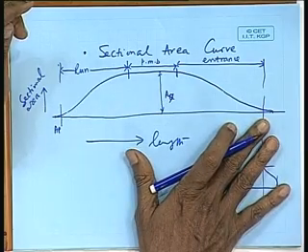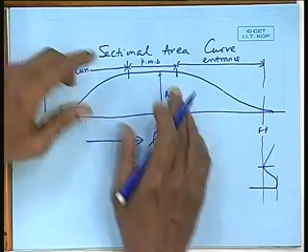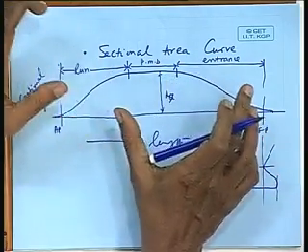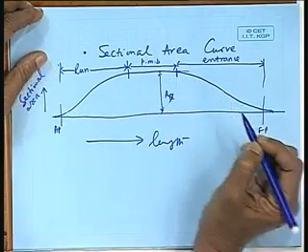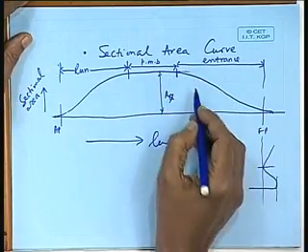Let us look at this diagram. If I change the parallel middle body, how will it look? Suppose I want to increase the PMB. See, if I have a longer parallel middle body, it is easier for me to manufacture, because I am manufacturing the same section for a longer length, is it not? So, I may be tempted from a production point of view to increase the parallel middle body. Let us say I take it up to here in the forward part.